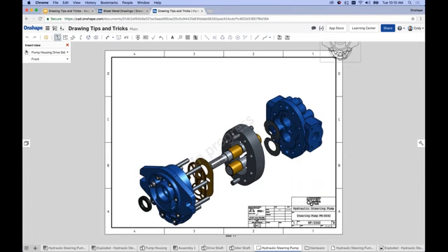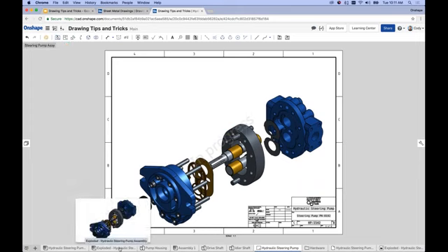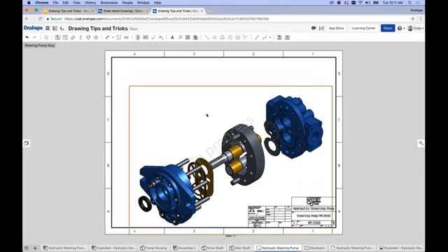How do you do assembly exploded view? And that's just this. There is no dedicated explode function in Onshape. All we did in this example is just copy the assembly, delete the mates, and manually grab the parts and drag them with the triad. So that's how you see the exploded view that was created here.